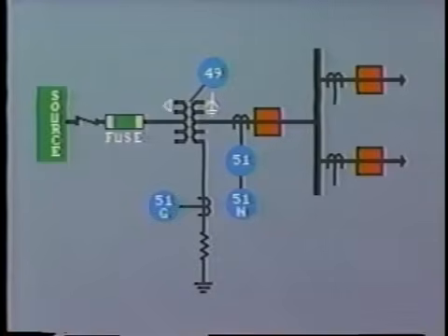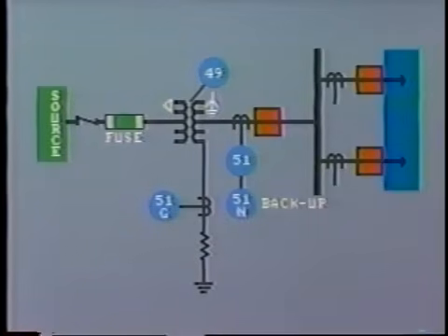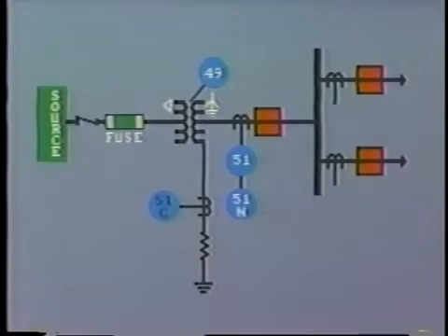Once again, the primary is delta connected and the secondary Y grounded. The basic protection is provided by overcurrent relays. A time overcurrent relay is installed on the outgoing secondary leads to protect the secondary winding against overload by tripping the secondary breaker. It is actually operating as a backup for any downstream protection on the feeders. The ground overcurrent relay 51G in the neutral will trip the secondary breaker in the event of a ground fault in either the transformer secondary winding or the connected feeders.